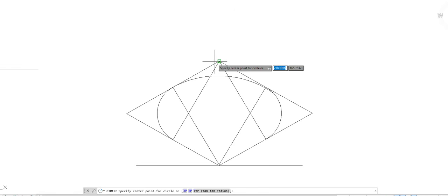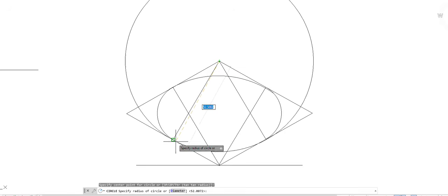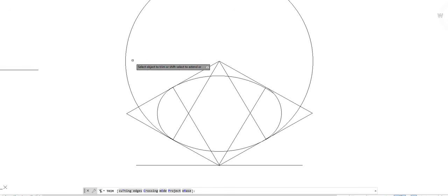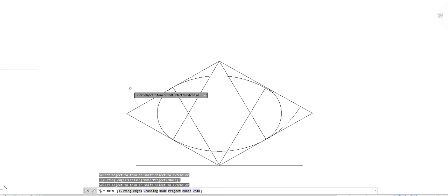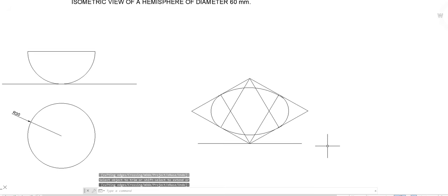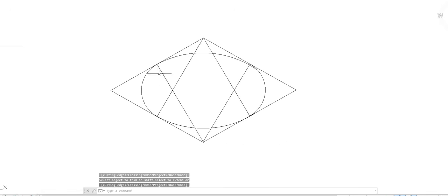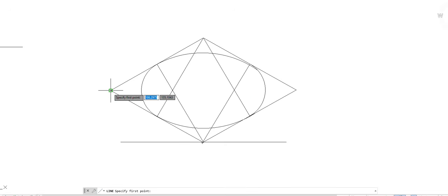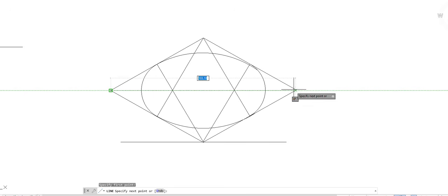Now draw one more arc. This point is the center and this has the radius. Now if you want, and if there is space here, we can give a bolt extension here. Otherwise, no need of that. So you got the body here, an ellipse here, and inside that just a rhombus. Now you want to draw a semicircle here. For that, you locate the centroid of that line.